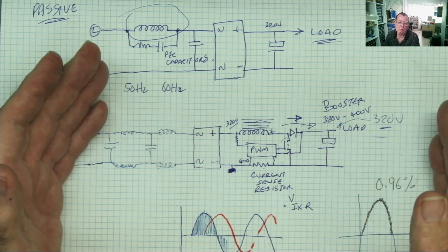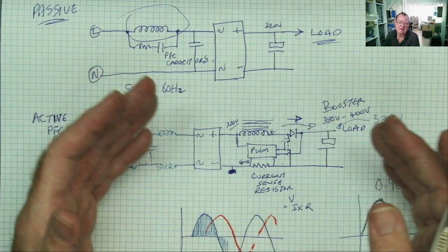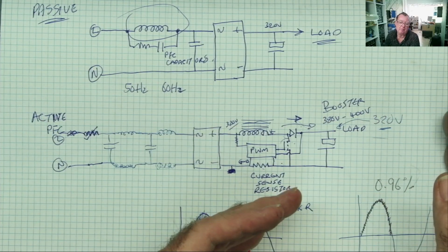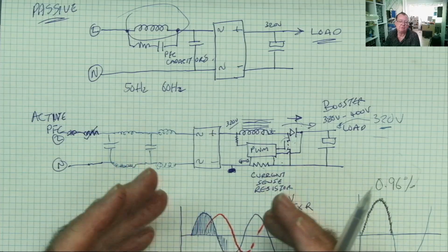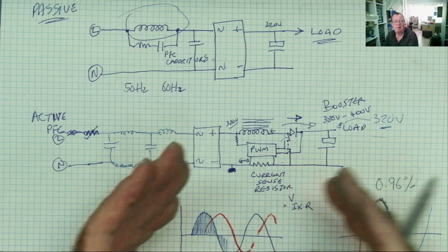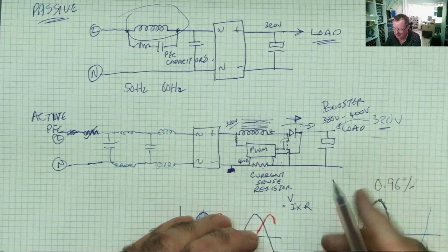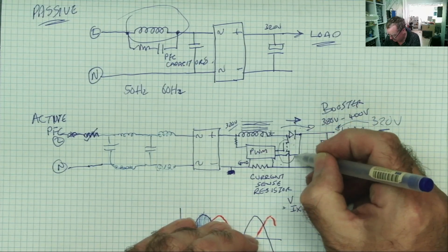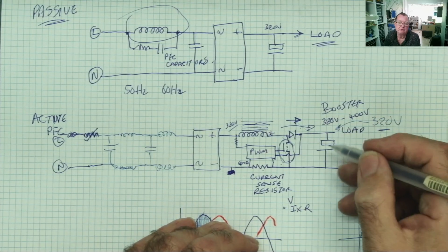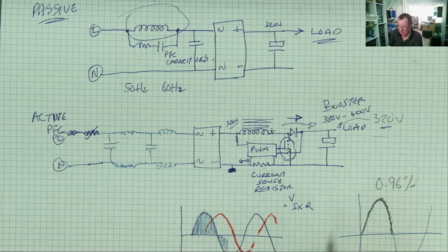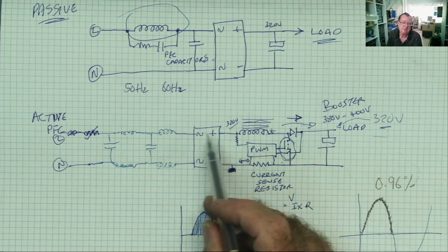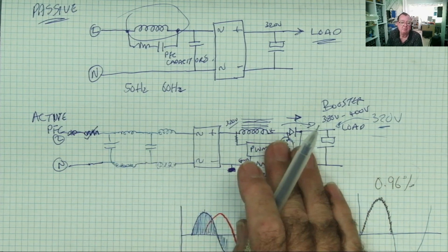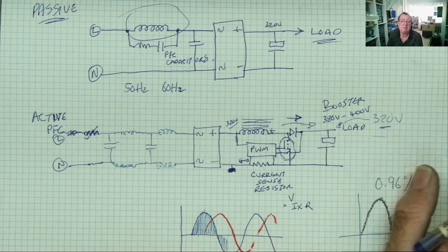Okay. That means that if you have a PFC problem and you have, for example, often in the TV, one circuit board which has both the PFC and the power supply and probably the circuit that generates the constant current for the LED backlighting as well, all in one, and you want to know, have I got a problem somewhere else as well as in the PFC? If you take this MOSFET or MOSFETs, pair of them, out, and this diode is okay, or you even bridge the diode, you short it, when you plug in, the PFC will not run, but the power supply probably will run.